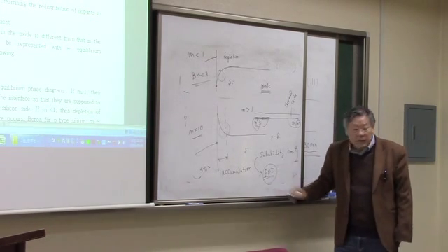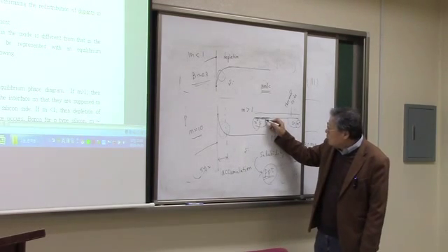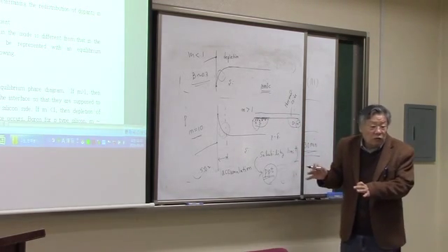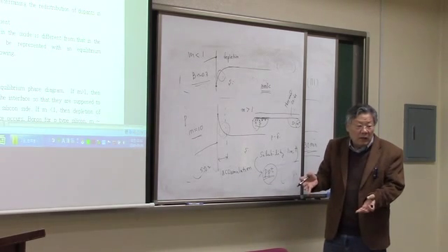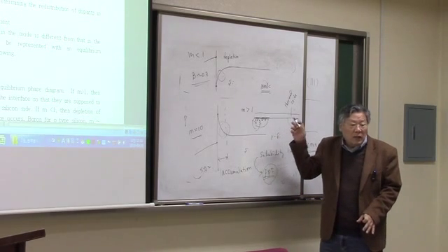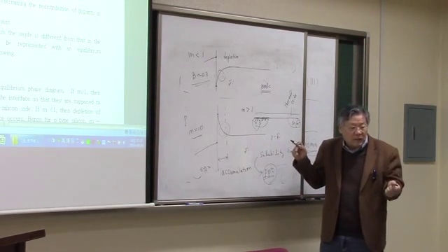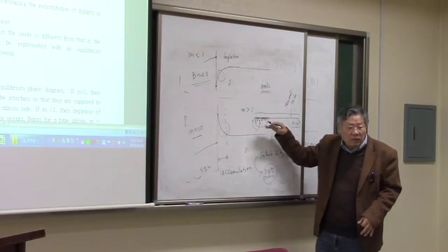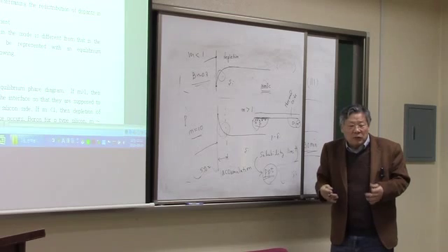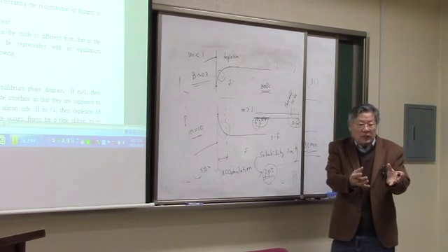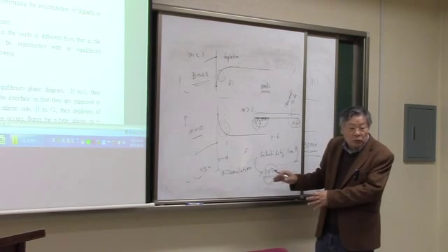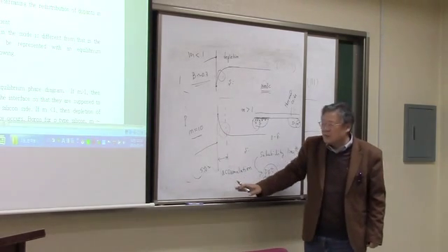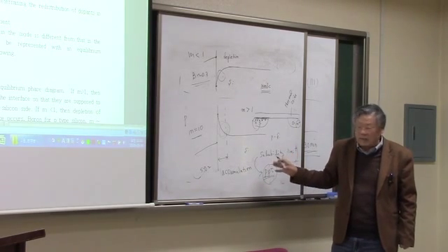And if you have a precipitation, then those precipitates are not going to be related to the resistance and whatsoever. It's a totally different material itself. So this precipitation is not only a defect, but also it is going to increase the resistance, decrease the conductivity of this material, even after the heavy doping of phosphorus. Some of the phosphorus is going to be consumed to make the precipitation like this. So this precipitation is not good in actual practice.